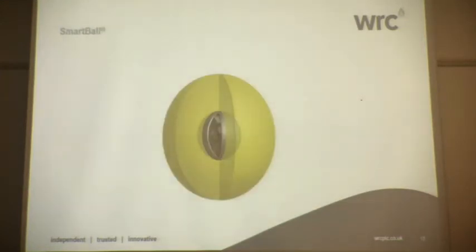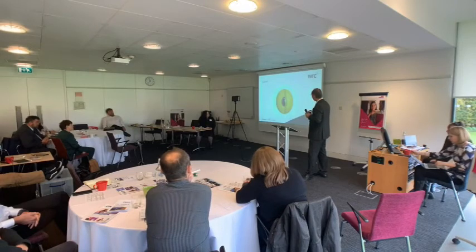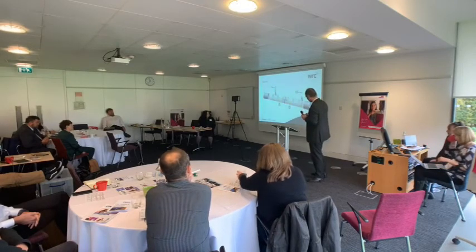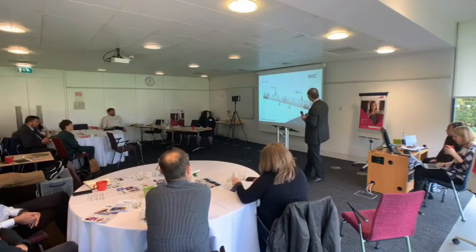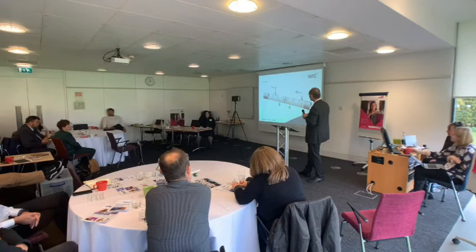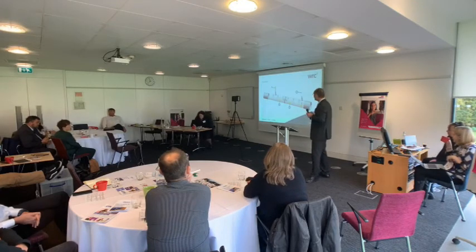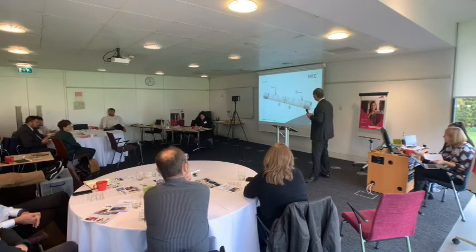SmartBall is a free-swimming acoustic device that logs acoustic data on board. It can be introduced into the network at an air valve location, for example, and extracted downstream many kilometers away using a capture device. It rolls along the bottom, collecting data as it goes, so the data is time-stamped. So we need to know where we are at specific times during the survey.